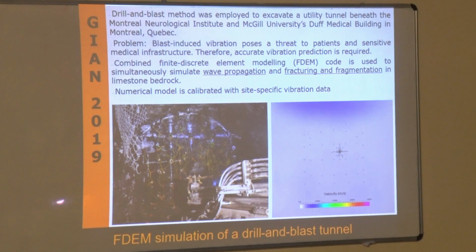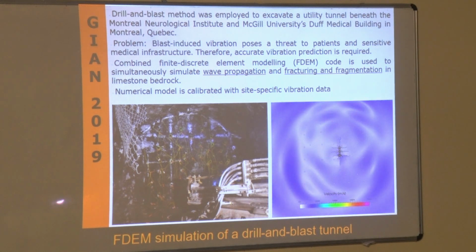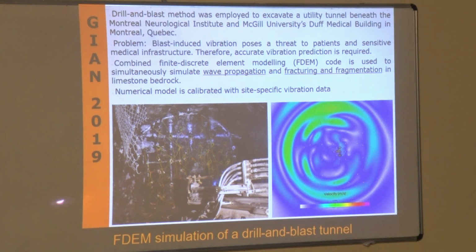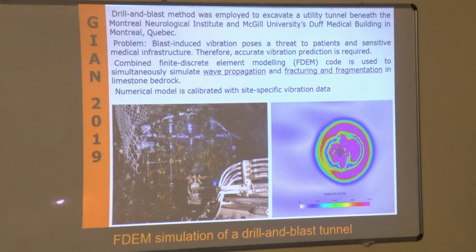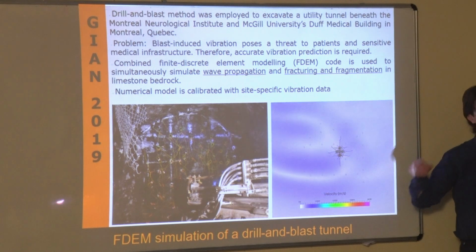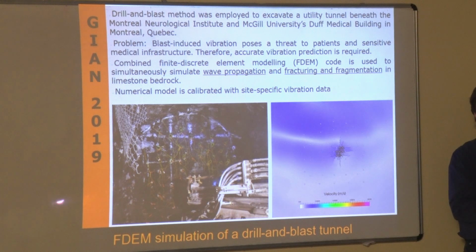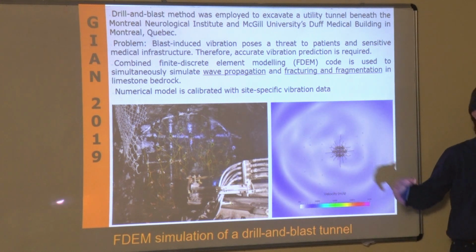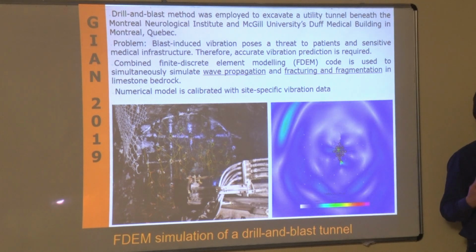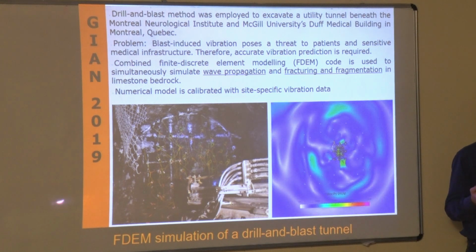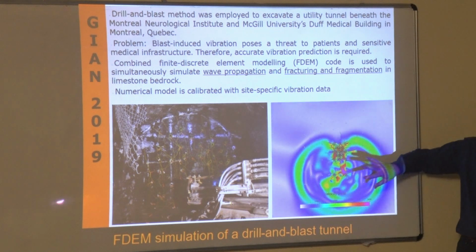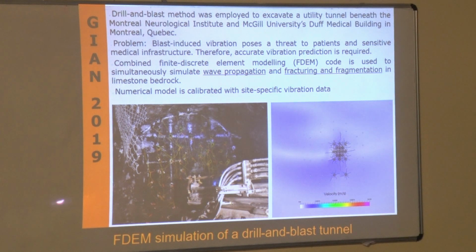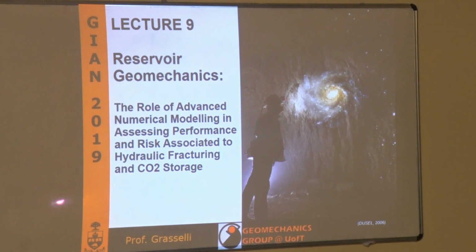And well, this is actually a cool system. You can start thinking about, or looking at, what is the fragmentation associated, for example, with blasting. You can see what is the change in the results if you change the delays between the different holes. What is the influence of actually having a cord detonation versus the electronic detonators that are much more precise? Is something that we can do better to actually have a much more controlled fragmentation during our blasting? All these are applications of new technologies, and those technologies do not need to prescribe the results, but they just need to make sure that the system is correctly calibrated, and let your system just work.